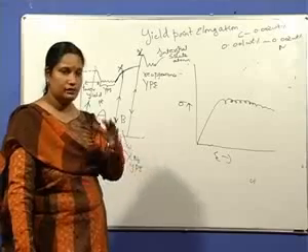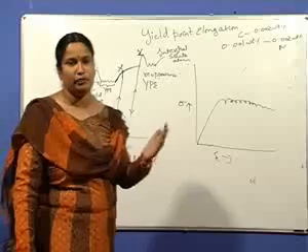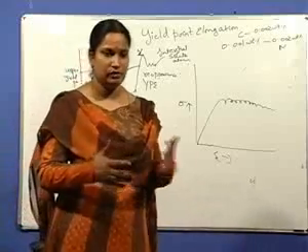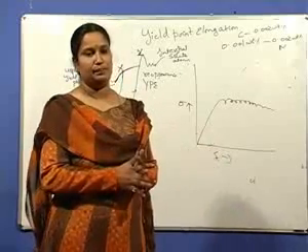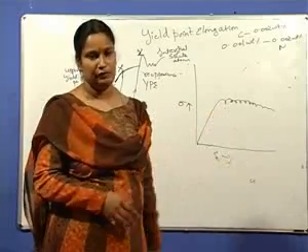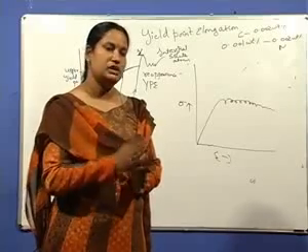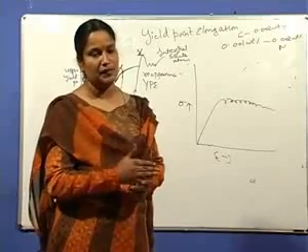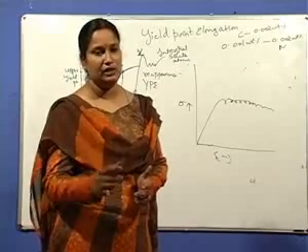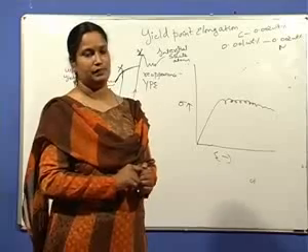But even if you are giving this amount of deformation, immediately you have to form the sheet metal part. Or else if you leave it for a few days, again this yield point phenomenon is seen. So as soon as skin pass rolling is given, immediately form the part, without giving enough time for carbon and nitrogen to again diffuse and form the atmospheres.